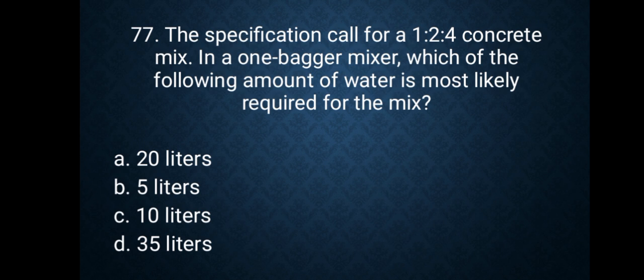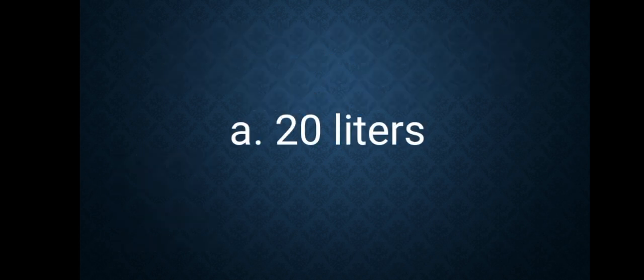So, number 77. The specification calls for a 1:4 concrete mix and a 1-bagger mixture. Which of the following amounts of water is most likely required for the mix? So, ada man ang mga choices. May 20, 5, 10, 35 liters. So, ang answer niya is A, 20 liters.